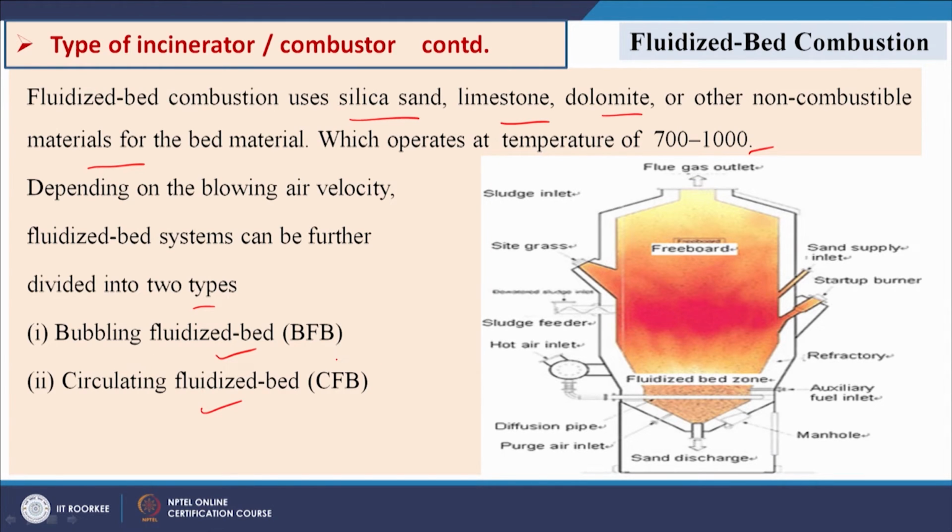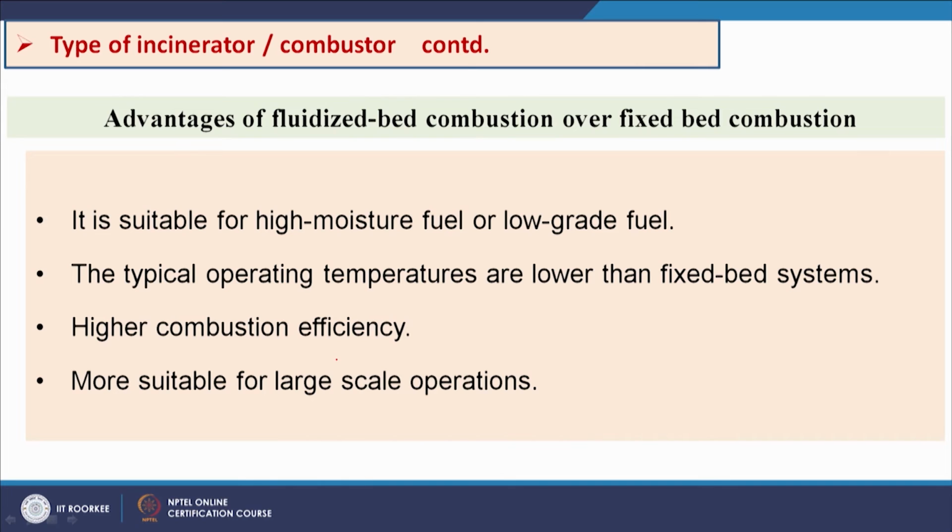So, this is the working of the fluidized bed combustion, and the advantages of fluidized bed combustion are these: it is suitable for high moisture fuel or low grade fuel. The typical operating temperatures are lower than fixed bed systems, it has higher combustion efficiency, and is more suitable for large scale operations.